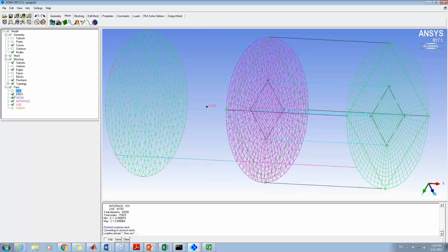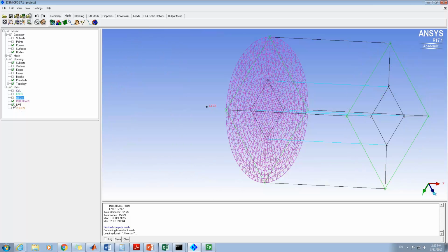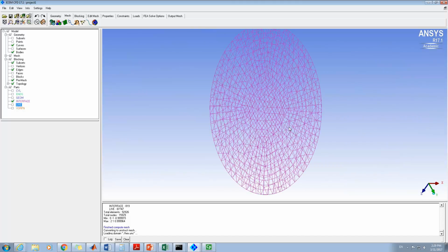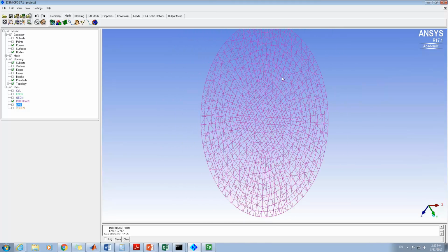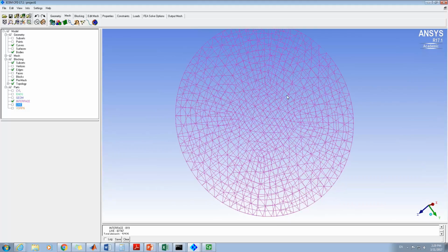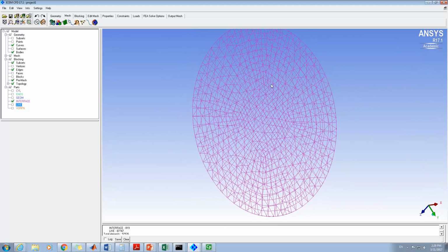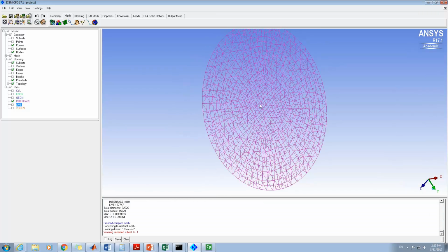So if I close the other geometries and only display this interface, you can see both unstructured mesh and structured mesh. They coexist here, right? That's very messy. So here, what I want to do is I will match those points. I will somehow adjust those unstructured mesh points so that they can match my structured mesh points.